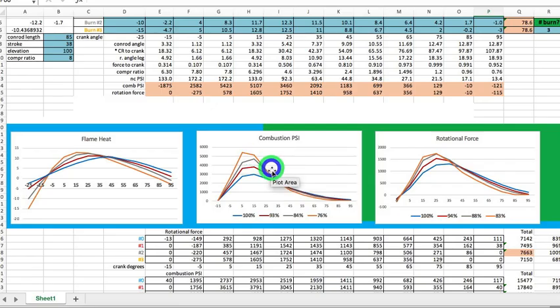With this excess pressure right here, we may be looking at some detonation. A lot of race teams will tune their engines to the point of detonation and then back off a bit. It all has to do with the burn time. What affects that? Squish velocity, compression, jetting, timing, and engine oil.